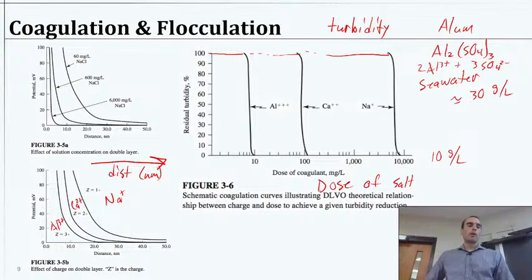This is also why, if you look at an estuary system, where you've got a river flowing into the ocean, at the estuary it probably looks kind of muddy. It's going to be somewhat turbid water, given that the river probably had a lot of sediments, a lot of suspended particles scattering the light. And then when you get way out into the open ocean, you will have reached a very salty condition that will have destabilized the particles. And so once you get past the area where they're all starting to aggregate and settle, it'll be very clear, ocean blue, like you can see pretty far through it. And this is exactly why.